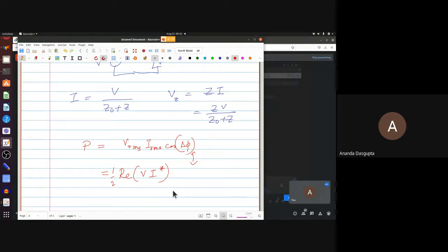So what we are actually using here are complex versions. And when you say V is V0 e to the j omega t, do you mean the real voltage V of t is V0 cosine of omega t plus phi? You would, if you were to use the convention that your actual voltage is this.